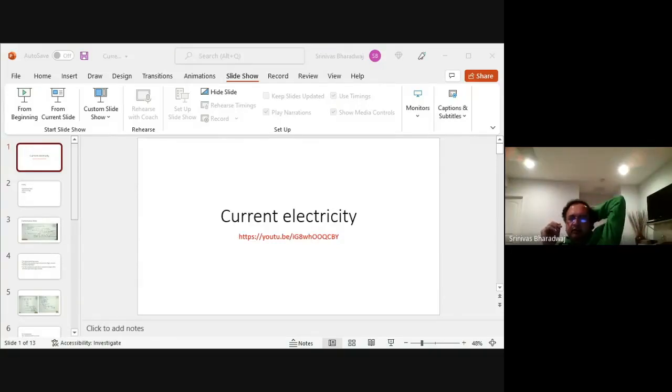Okay, so there is a potential drop inside the battery also. So the load will get a slightly lower voltage, because of the potential drop when you connect and close a circuit. Now if you had E, the electromotive force, then you have to add minus I RL minus I R. So you already know, then you have to solve these equations.